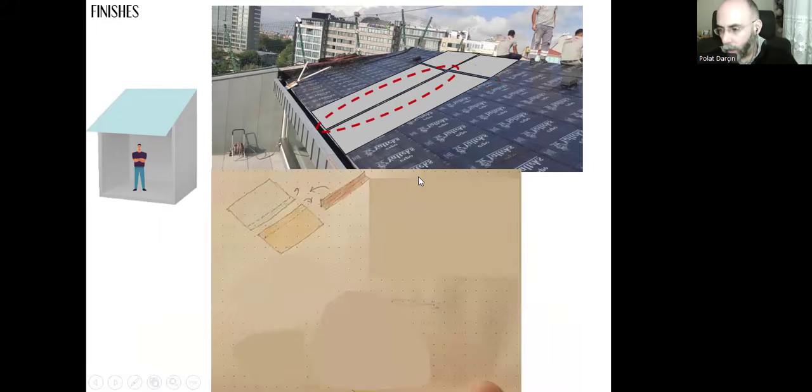What about this vertical line, vertical joint here? In order to fix these two panels together, again, we need to fold the sides of these panels. Also, we are going to use an L-shaped third piece. First, we get the piece and we can nail this piece only at one point on the surface of the insulation. Here, as you can see, this L-shaped piece is nailed using only one nail or bolted maybe. So this is fixed, and the side of this left panel is folded. The side of this right panel is also folded.